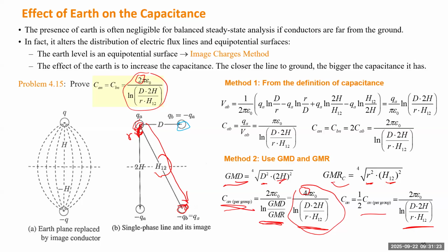So when they connect a transmission line to energize the transmission line, because they cannot add load to the line, they will connect to a line with no load. For such cases, the far end will create a very high voltage because most of the lines are underground, so they have a capacitance. So you can imagine when you connect a line, the line is connected to a capacitor. So the line may have an overvoltage problem.